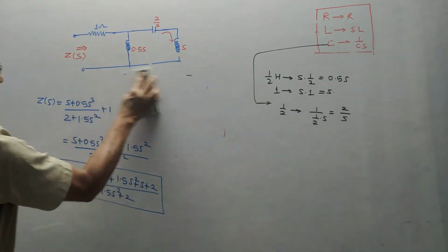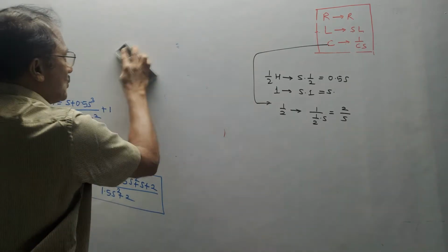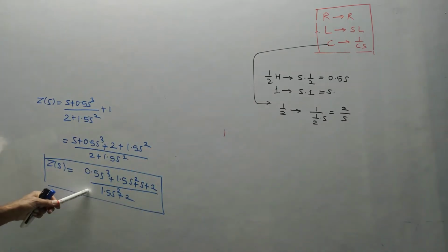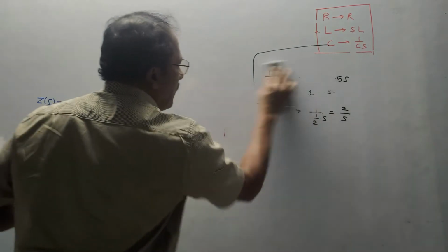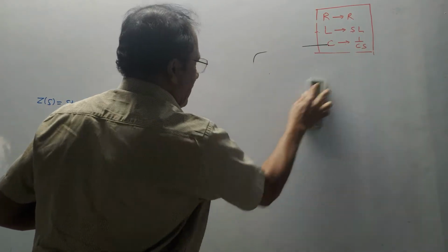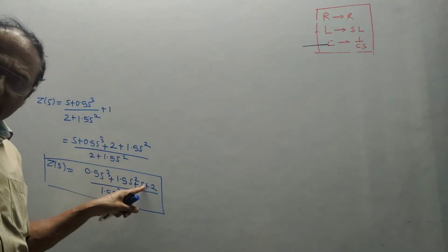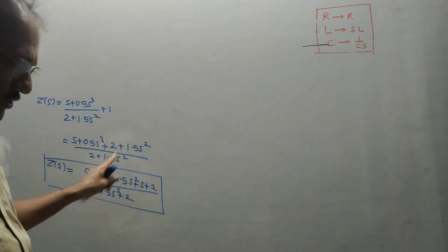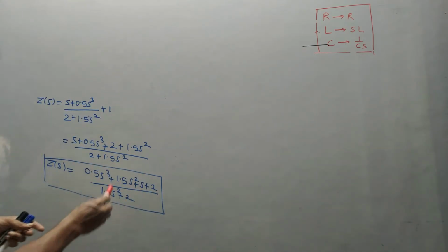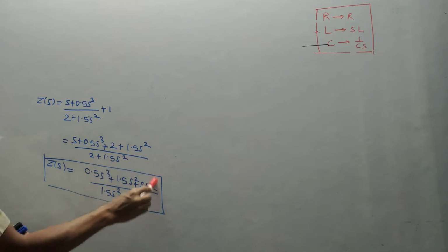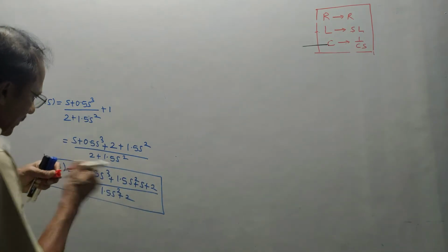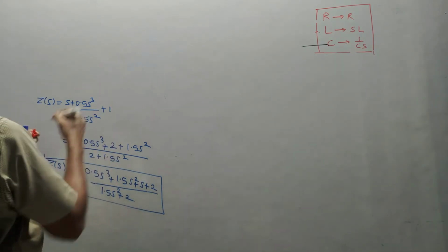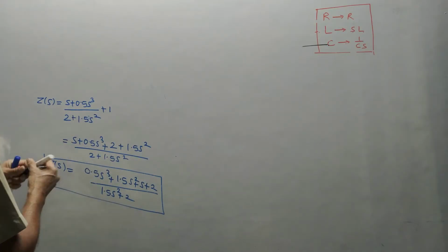Alright. So in the present numerical, it is asked to calculate driving point impedance that we did, and we have to plot the pole zero diagram. How to draw the pole zero diagram? For drawing the pole zero diagram, we need to calculate the roots of the numerator and the roots of the denominator. Strictly do the calculations on the calculator. So roots of the numerator term are known as zeros. So I will do the calculation on the calculator. Directly I will write the values.